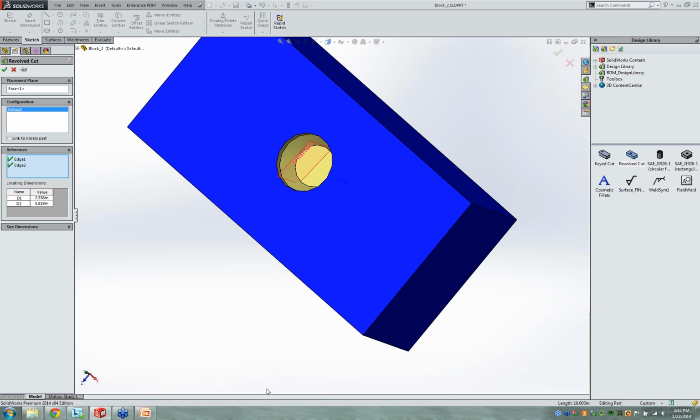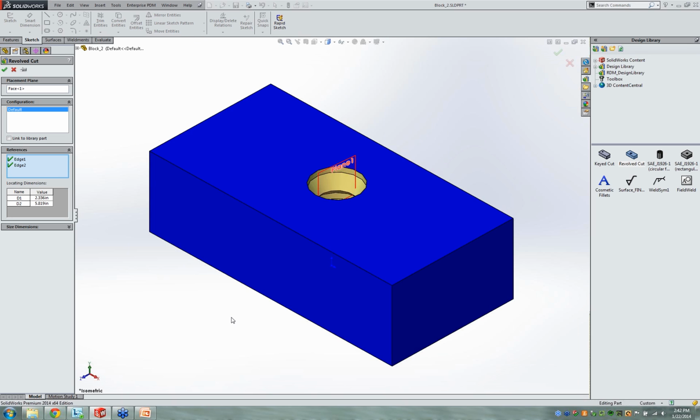You know, Revolve cuts, you can even do it with lofts, lofted cuts, you can do extrudes. It's not limited to cut features. You can actually be adding material as well in these. It's all the same concept though, just making sure you're tracking your references as we go through and create these, and understanding why a certain reference is being created. So certainly something to play around with, not something you're going to get right off the bat, but certainly something that will benefit once it's done correctly.